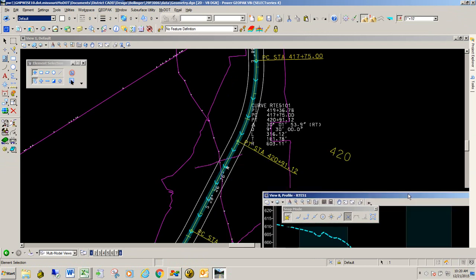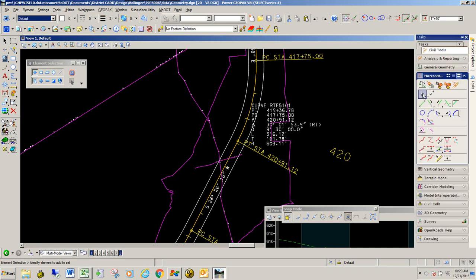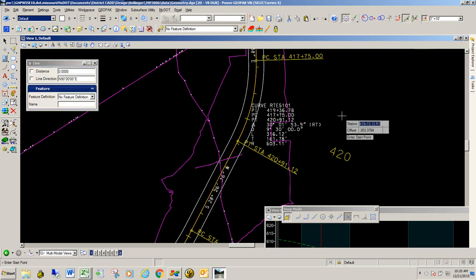I'm going to go ahead and just get that out of the way. I'm going to click in the plan view. I'm going to go up to my Civil AccuDraw and make it active. I also have the option of station offset active. I'm going to go to some horizontal tool, and when I do that, you can see that the station offset is on my cursor. And I'm going to hit the O button to tell it what chain I want the